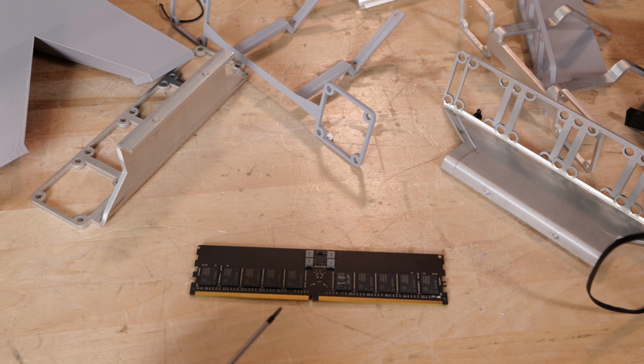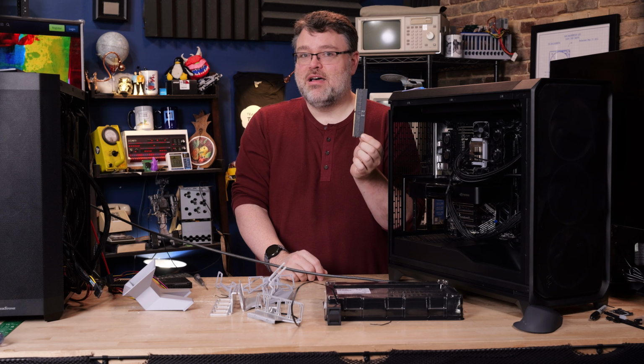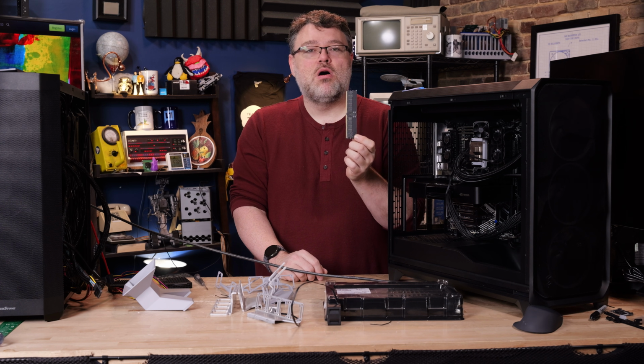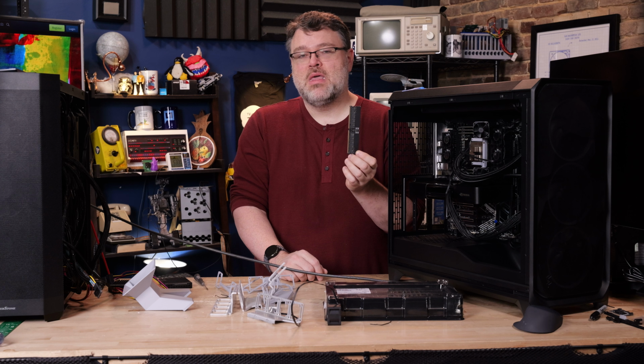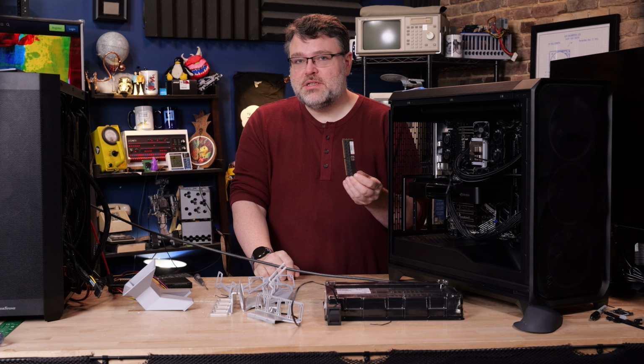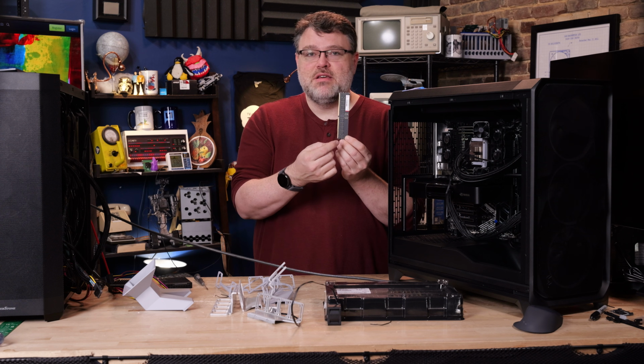It's storing and retrieving more data from the memory controller and the CPU to the DIMM. So when people say DDR5 has ECC, what they often mean is the on-die ECC, which does not protect you from signal integrity issues and most types of thermal instability, platform firmware bugs, as we're going to have to talk about with ASUS, that type of thing.